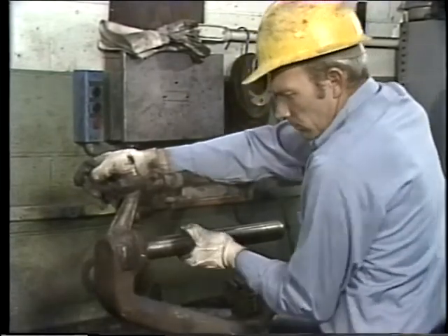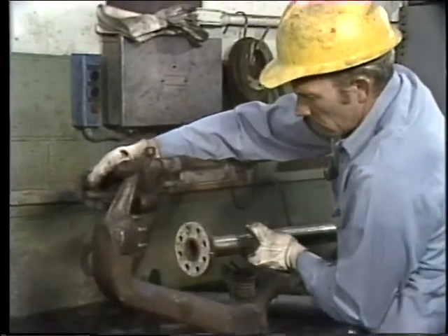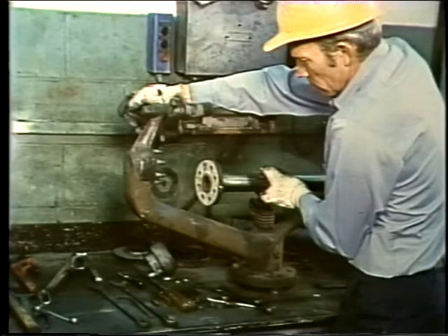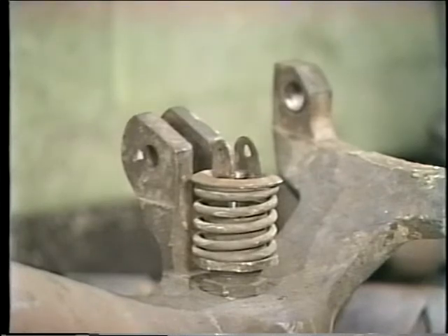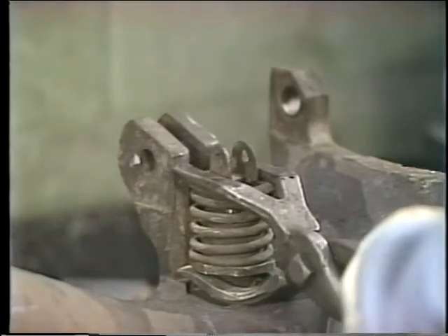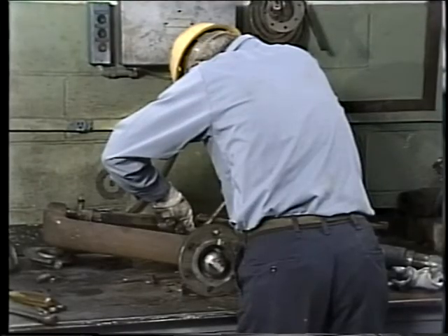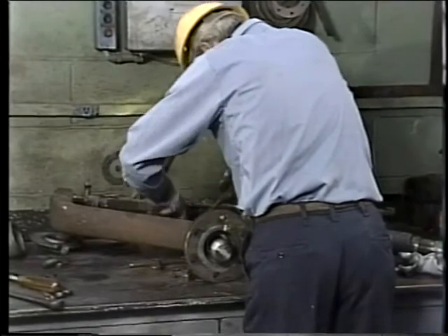It's just a matter of unbolting the flange, starting with the nut that holds the bearing in place, then loosening all the rest. On this soot blower, all that's left to do to complete the teardown is to take the valve apart. Like most soot blowers of this kind, all that's needed is to compress the valve spring and slide off the keeper. If the valve packing isn't too tight, the stem and disc can be pushed on out.